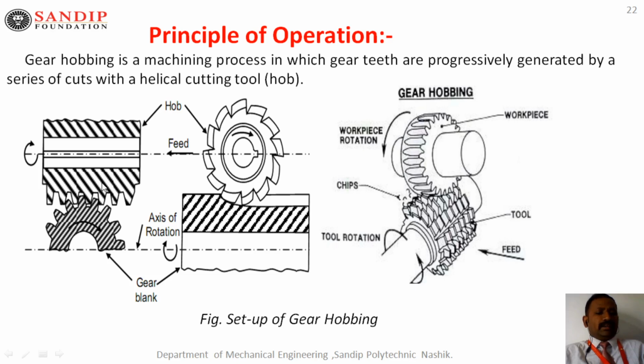Helical teeth are there, and those teeth have a number of slots. So the figure is nothing but this. Here the helical teeth and these slots are there. So these unidirectional cutting edges are provided, continuously rotating with the gear blank, and the gear blank forms these slots as teeth on the periphery. That is the gear manufacturing method.